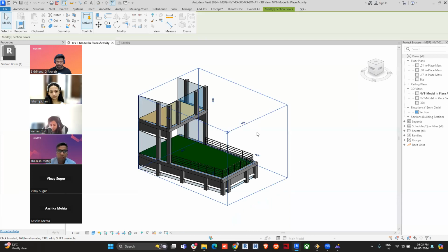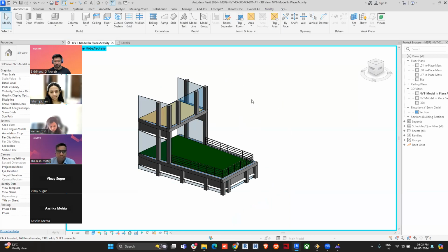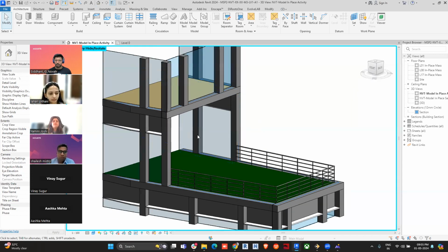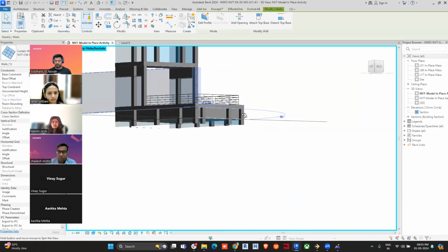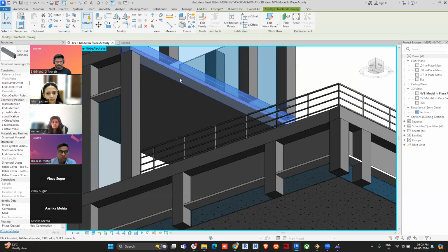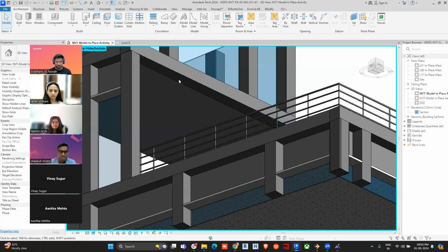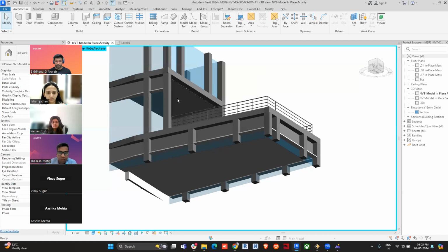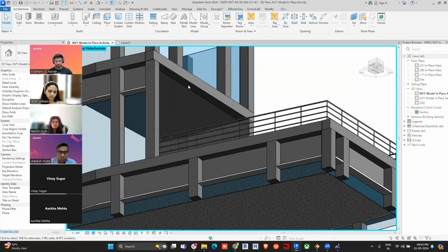I'll just select this and press HH to temporarily hide this box. I really don't want it. Now I want that particular sweep to be in a way that it will have the bottom of this as the reference plane. So if I create something above it, it will be there. Just consider we are using this bottom as a reference plane. I'll explain why and how.